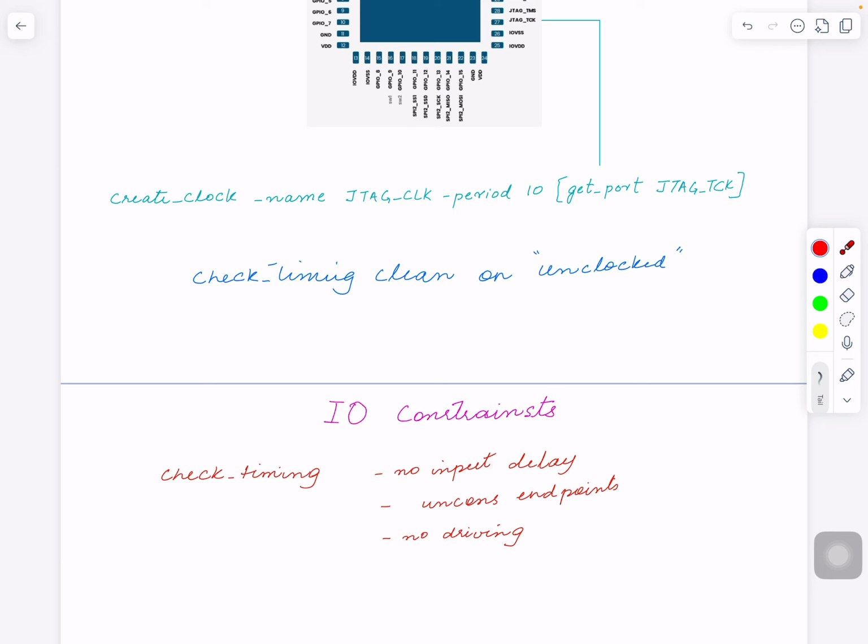And even though we created the clock definition and most of the endpoints should be gone because they are getting clock definitions, I was really expecting the output ports to be among the major unconstrained ones. But we figured out when we did this report, we did a verbose on that, and we did all fan in to some of those to see where those clock pins are coming back to. And we figured out a lot of stuff was dangling, not connected, or actually the constants were propagating. So they were tool tie-offs: the input of a flop was tied off, and then constants were propagating.